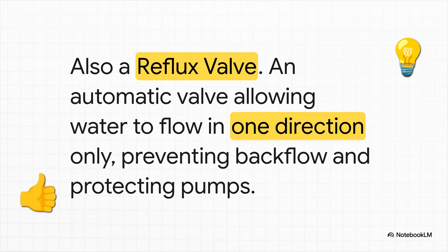Why do you need this? Well, imagine you have a pump pushing water up a hill. If that pump suddenly stops, all that water is going to want to rush back down. The check valve slams shut and stops it, protecting the pump from being spun backward and destroyed.